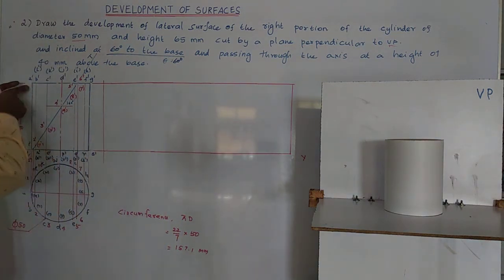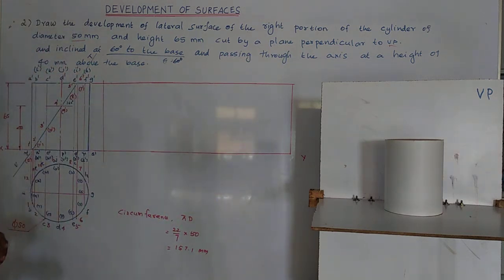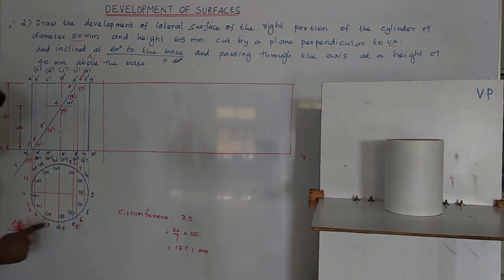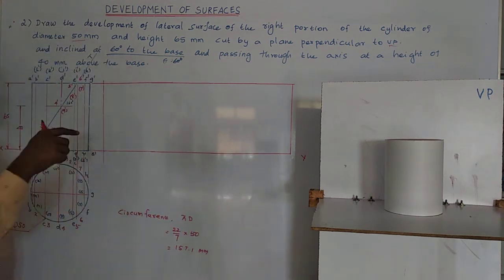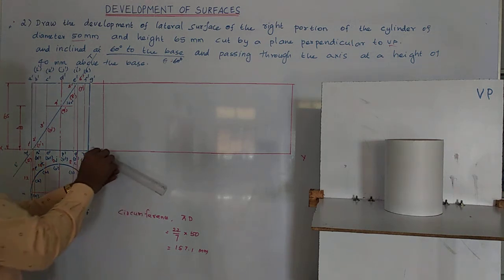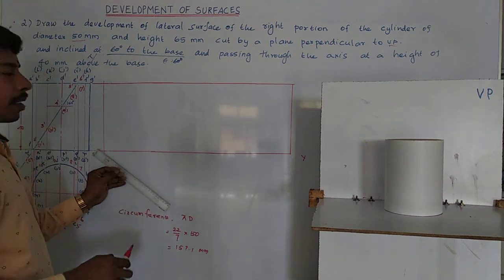I am going to cut here and spread over this plane surface. Then I mark all these 12 edges here. So here in the circle, I divide this circumference into 12 segments. So I spread over here. This circumference also I have to divide into 12 equal segments. For that, from the starting line, from here to here, I divide into 12 segments.